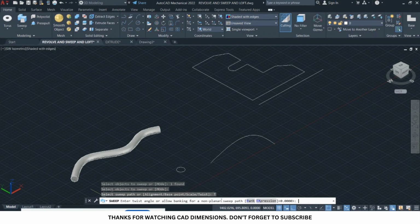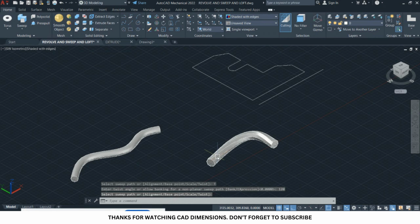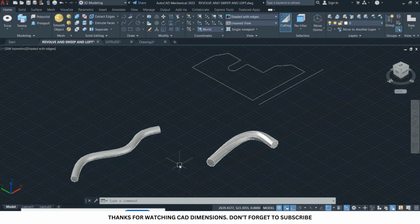Let's try the twist. For the twist, you are basically creating a twist with a shape that you want. So I want to create a twist of, let's say, 120 degrees. Then I select this path. As the polygon shape is being swept along the path, it is actually twisting.